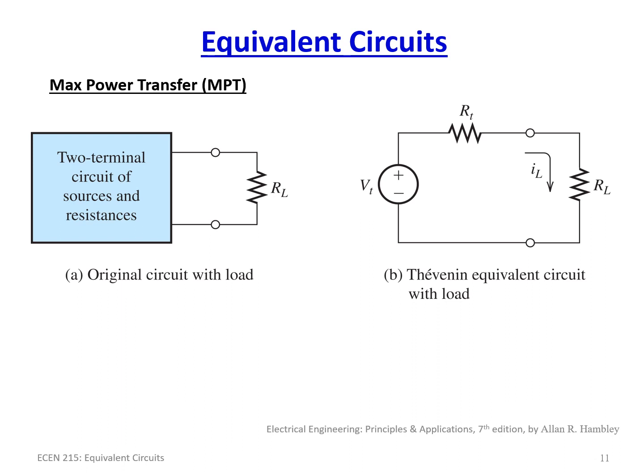So RT and VT are fixed, and so the question is, what is the maximum load that you can attach to the circuit to actually transfer the most power? So you're looking for a maximum at this point, a maximum value that you can get. So power in the load is simply, remember, power is voltage times current. So that's what we're really looking for here. And we're looking for the maximizing RL, or what is the value of RL that maximizes the power.